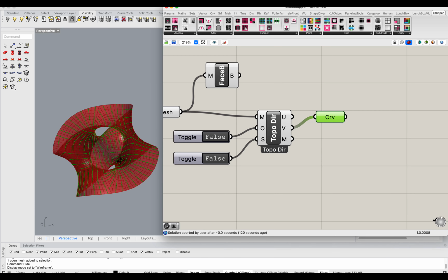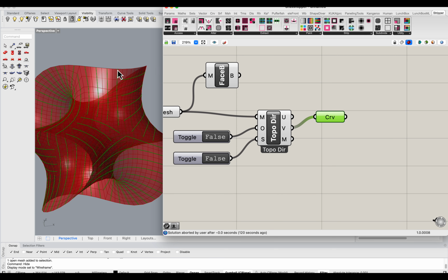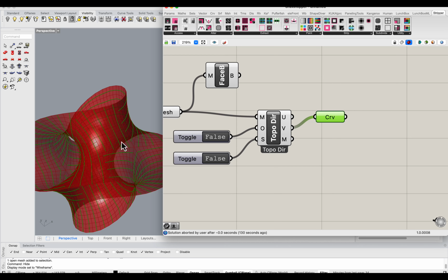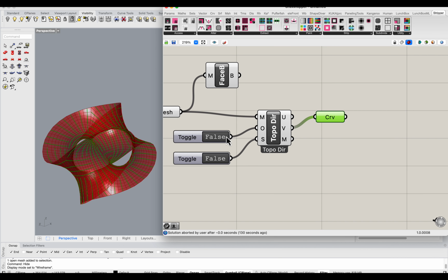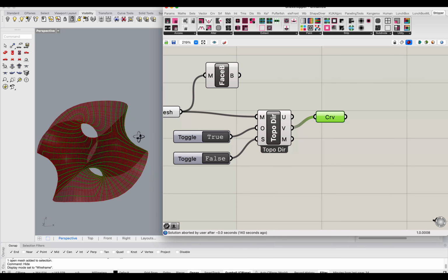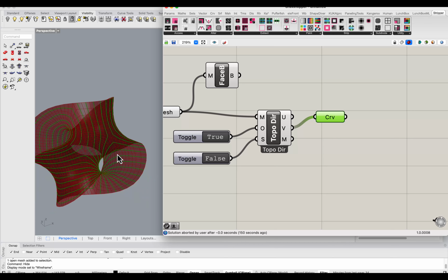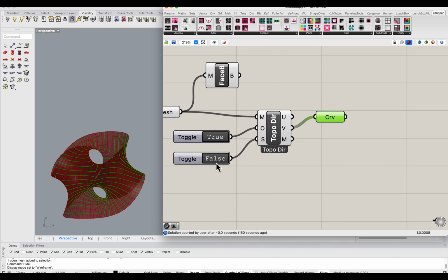With these curvature directions, right now you can see they're a bit more patched, so we don't get a linear distribution of elements, it's kind of like a patchwork. If you toggle some of these tools, you can see that the direction calculation is actually changing. What we want to do is set the reordering to true, so that it first fixes the direction of flow in the input mesh and we get nicer strips like this.